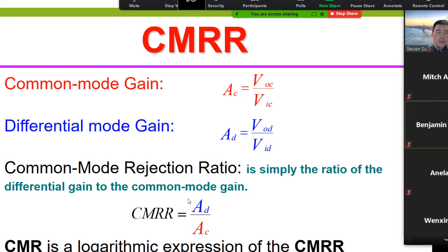We normally want the CMRR to be as big as possible. For a very good instrumentation amplifier, it reaches 10^6, which is quite big, meaning AD over AC is 10^6. Unfortunately, this semester you cannot measure it because you cannot implement it, but you can still simulate. Based on simulation, you can calculate the CMRR because Multisim is quite good and also considers some real issues.